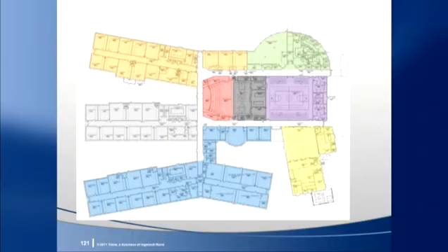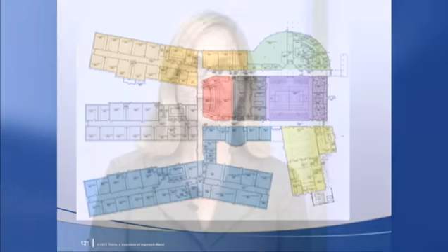to. For example, in this high school, a dedicated outdoor air handling unit might be located to serve a wing of a classroom, such as the middle wing on the left-hand side colored gray. The water-to-water heat pump might be installed in a small closet in the wing to minimize the cost of piping and ductwork. We packed a lot into this broadcast, but hopefully you can use the 4 primary goals that we discussed to analyze the options on your next dedicated outdoor air system project.